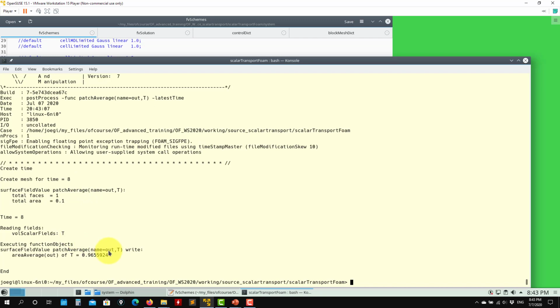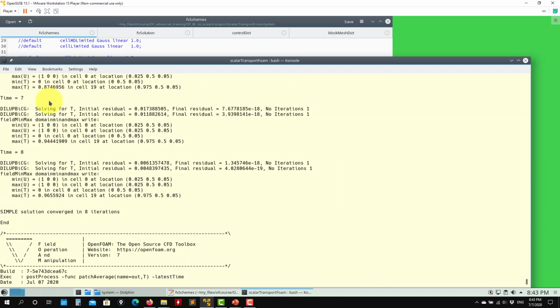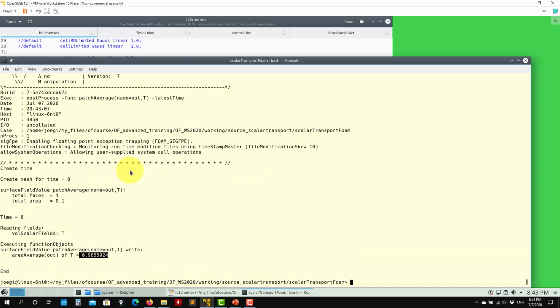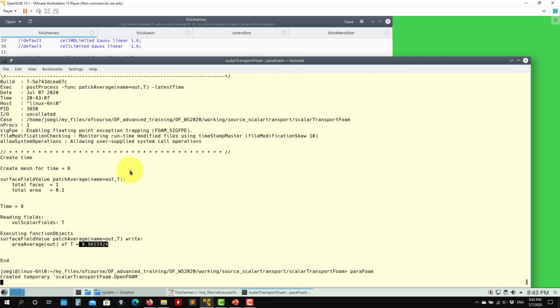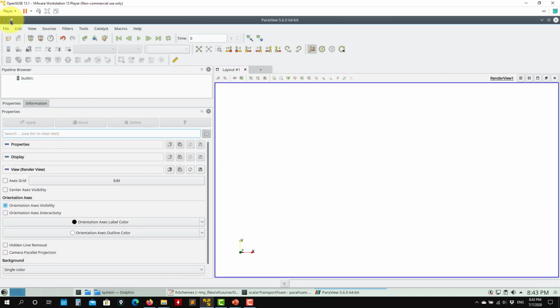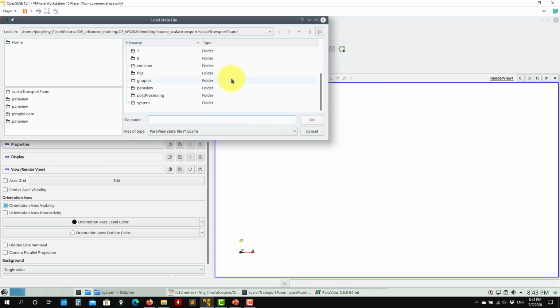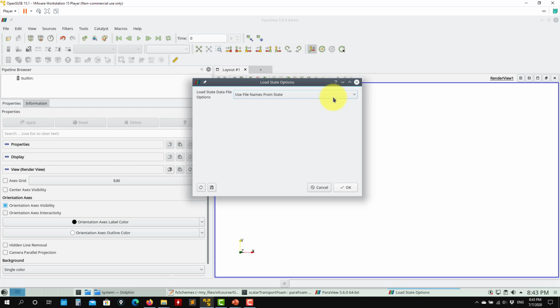So you see that in 8 iterations it converges very close, and see that we don't have those oscillations there. So this is another example just to support when I tell you that I really like the min-mod. It has very good properties, very stable. Okay, it's less accurate like any other TVD, but it's much better than the upwind.